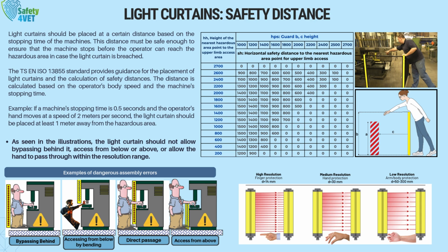There are different types of light curtains, depending on their application. Single-beam safety light barriers are used to secure smaller areas, such as access points like machine entrances or doors. Multi-beam safety light barriers offer body protection, monitoring, and securing larger areas, such as conveyors or around large machines.